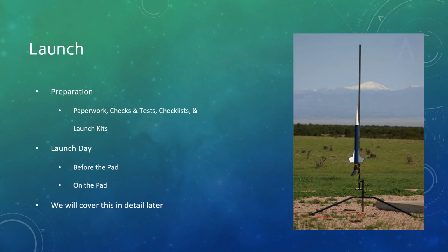So once you're on the pad, first things first, you load your rocket onto the launch rail. You want to take the 2 wires that lead to the control box that the range safety officer uses to start your engine, and just take the 2 leads and tap them together just to make sure there's no static electricity. You don't want to hook those up to your igniter when it's in the engine and start it while you're there.